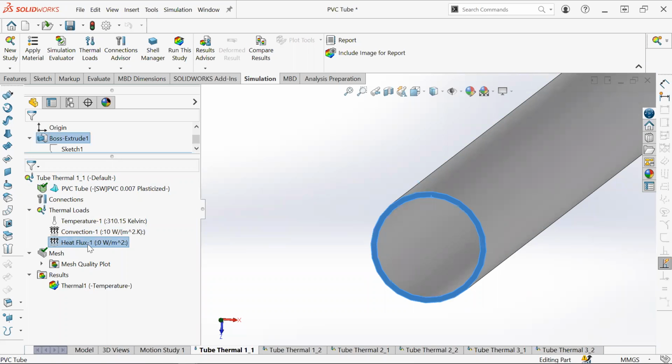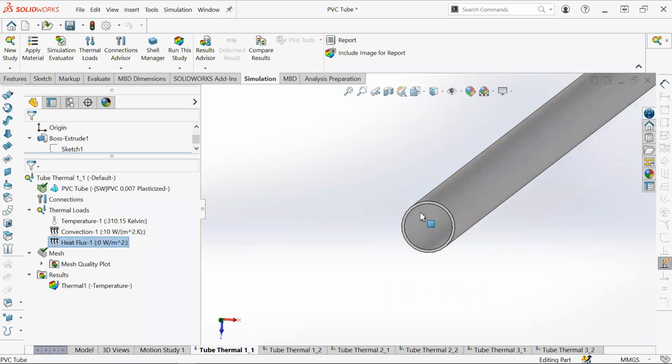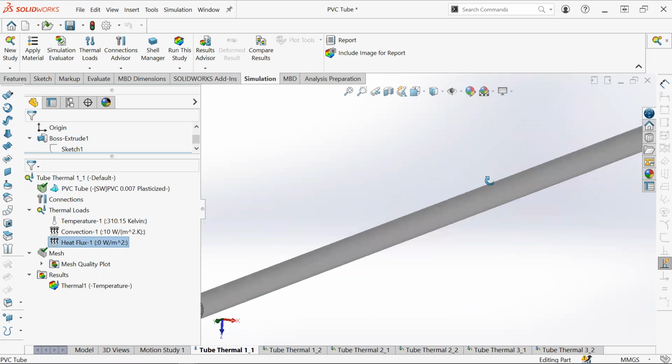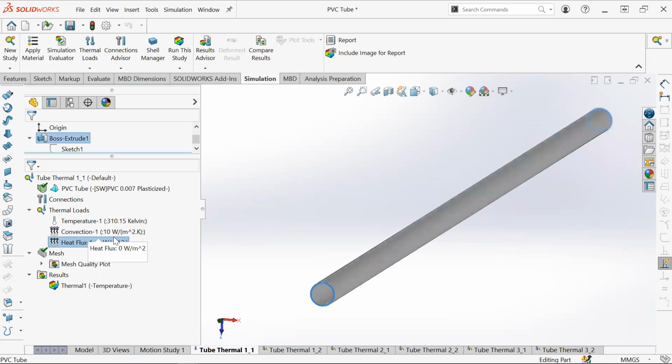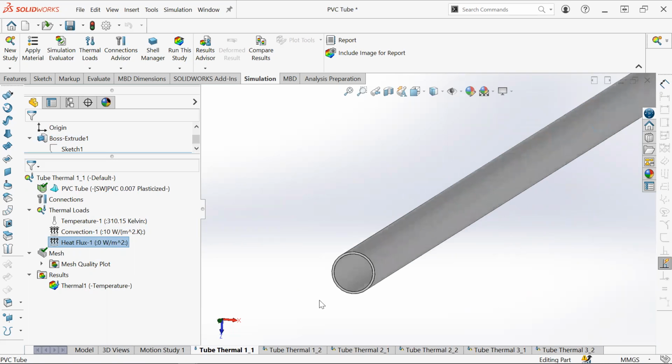Although I don't think this should matter too much. You can honestly make do without this. I just added it, and it seemed to work fine for me, so I just kept it in, but you guys don't really need those, I believe. The results shouldn't differ that much because the surface area is so small anyway. But you can make any parts insulated by just setting this heat flux to 0. So that might be something you want to consider, having some surfaces where there's no heat loss. We're assuming some surfaces have no heat loss. This is one of the assumptions I made as well, and you should include it in your proposal or in your results section.